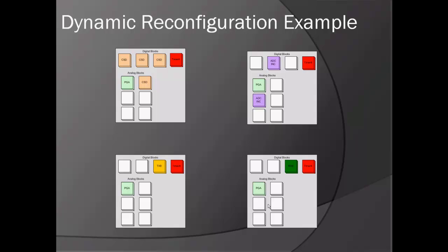Dynamic reconfiguration is a powerful tool that allows you to dynamically reuse resources in the PSoC device. The key to dynamic reconfiguration is understanding that you don't need all your hardware functions active 100% of the time. Again, this allows you to get the maximum use out of the PSoC. Much more detail on this can be found in the associated application note, AN2104.